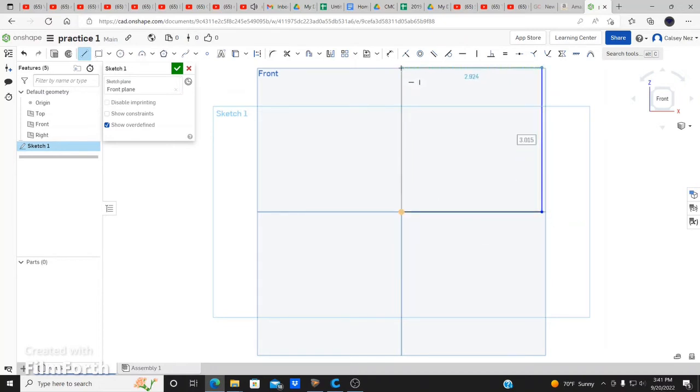But once I hit the end point right here, you notice that it changes colors. It went from a hidden line to yellow. The reason is that the software has a secondary aid that will help you along the way. If you want to look for the edge of the line, it'll click in and know that you will stop right there. If you want the center of the line, it'll click that too. If you go over here, you'll see a center line come up. Don't click anything else. That's the big issue for new beginners, because if you select it, you're ruining your spot, and you end up with multiple items that make a mess. That's a no. Do not click anything else until I say so. Until then, you'll continue on.